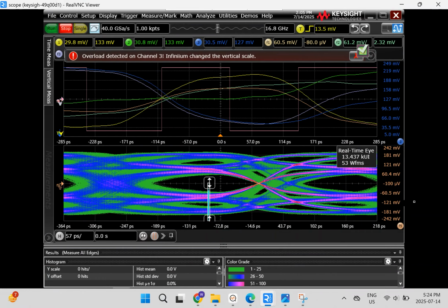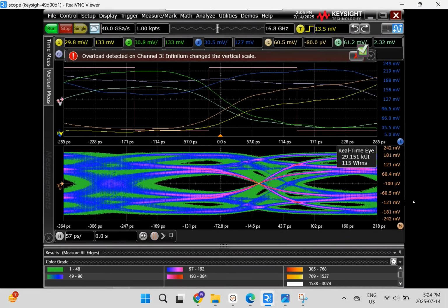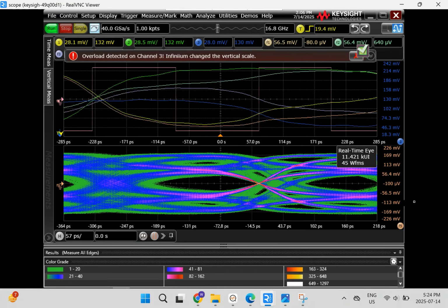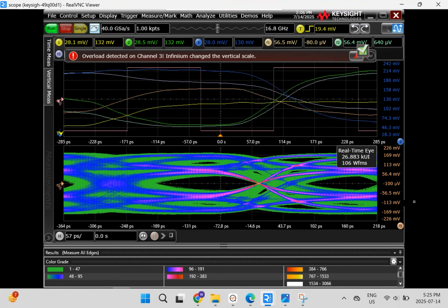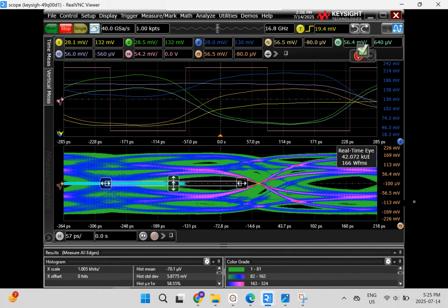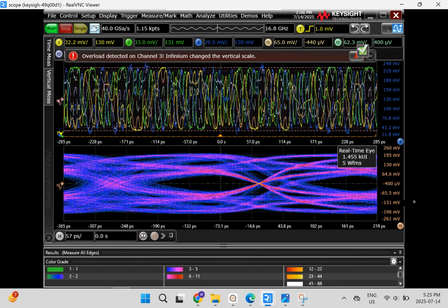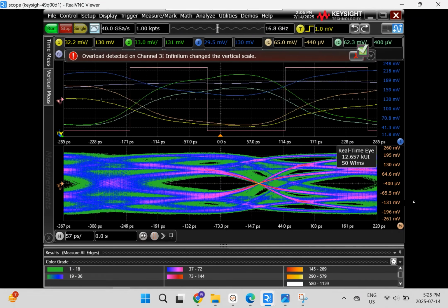required settings. So what you can see here on the screen is that this is really an iterative process. The script is trying a different combination of these parameters and then measuring the eye. And then if the eye is not the desired width and height, then the software tries a different set of parameters. And these parameters are constantly varied until the optimal combination is achieved, which gives us the desired width and